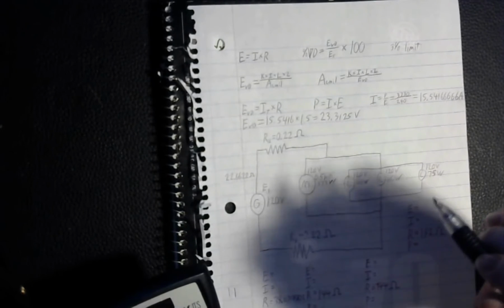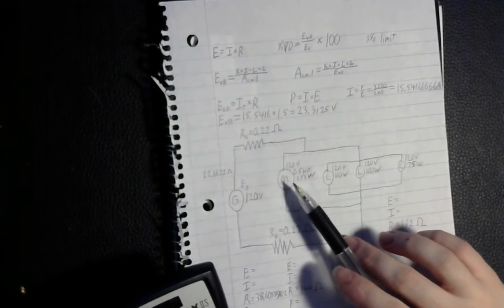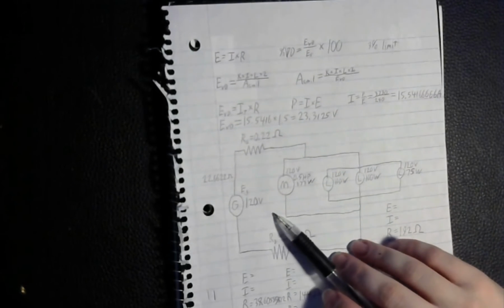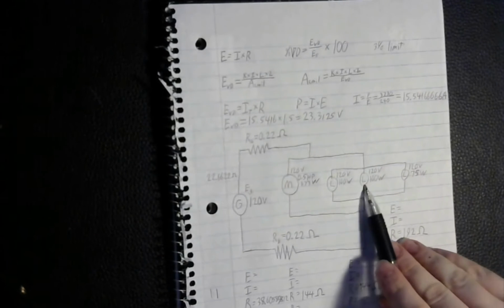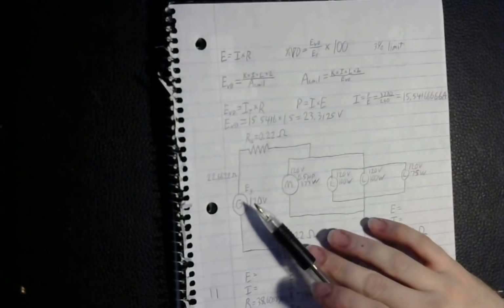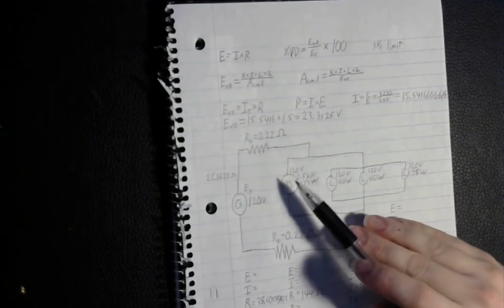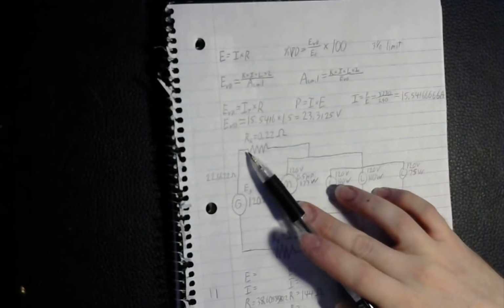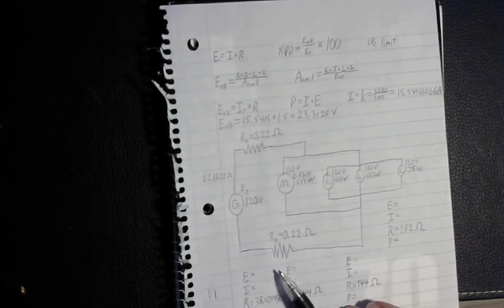Sort of. What you need to do is figure out what the actual voltage is here, because for lesson 4 it goes into voltage drops. So even though all of these loads are rated for 120 volts and your generator's outputting 120 volts, that's not the voltage that's actually reaching these loads. You've got a drop because there's some resistance in your wire.